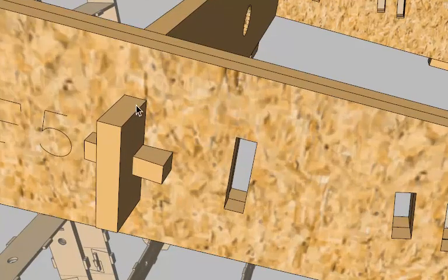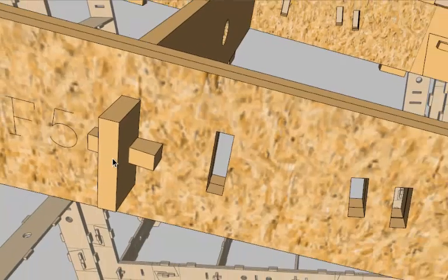Obviously, when we come to CNC machine these, there's going to be variations in material thickness, and also the cutter is going to leave a radius, a fillet in effect, in these corners, because with a round cutter on a CNC machine you can't create a completely square corner. And the normal process for handling this is to add what's called dogbones, where we create a little fillet radius here so the tool can move into there, leaving enough space in the corner for the parts to be assembled. Equally, to account for variations in the timber that you're cutting it from, it's normal to leave a gap here, an allowance all the way around these parts.